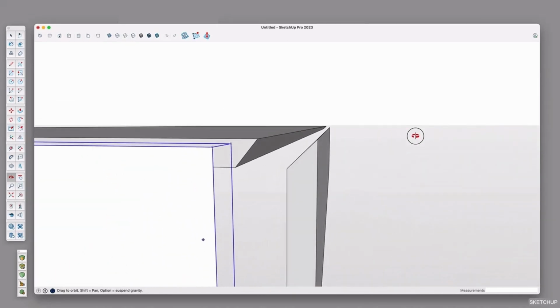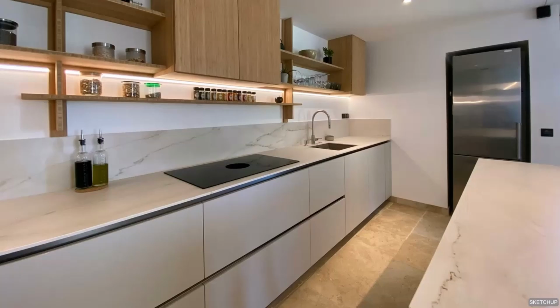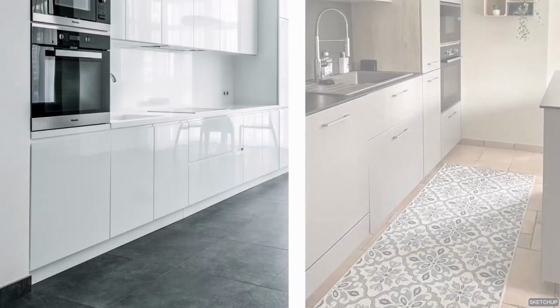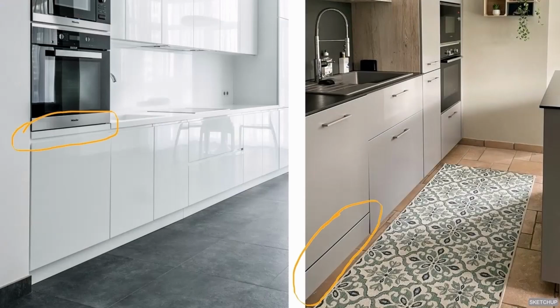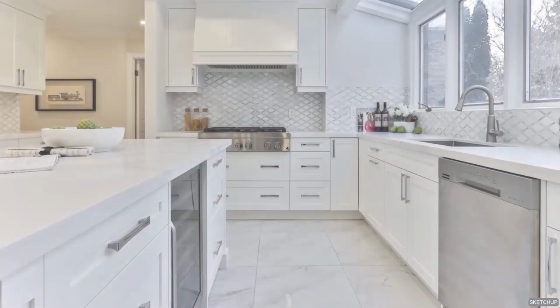It's crucial to note that changing your benchtop height during the process is tricky, as it will impact the appearance of your appliances and the design of your overall cabinetry fronts and drawers, and you may need to incorporate fillers to address any gaps. So I recommend deciding on that very early on.